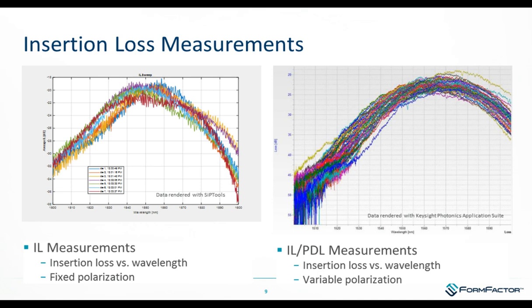There would be this test sequence, which I have a video to illustrate in a minute, that shows the wafer would step the fibers from DUT to DUT, do an alignment with the optical scan, and then execute one of these measurement sequences. And then here's all the data from multiple die laid on top of each other.